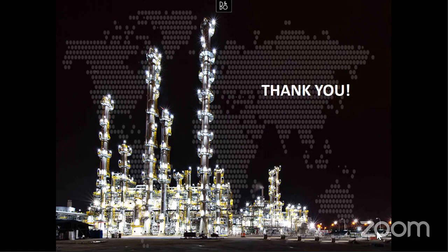So the communications can be affected by that? What will affect the communication are other things like cranes and big metal things. I actually had somebody who bought a system and took our gateway and put it in a metal cage. That's a Faraday shield. It's not going to work. You can't do that. But bigger issues are people who have a lot of RF interference. I had one guy who had some kind of microwave machine, and it was just a lot of noise. They couldn't get anybody's communication working in their factory.